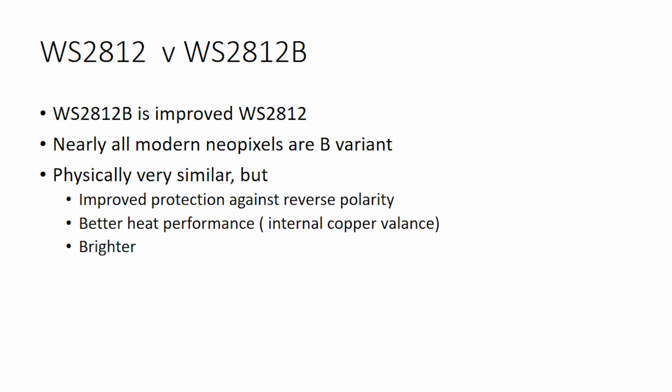Because sometimes a bench power supply, if you put it on to 5 volts, it will shoot up to 5.5, 5.7 volts, and then down to 4.7, and then back up to 5.1, and then down, and it will settle after a couple of oscillations. And that bounce, that overshoot can kill a NeoPixel. So if you're killing NeoPixels and you're using a mains power supply, that might be the reason that you're doing it. So I'm just sort of throwing that one in.